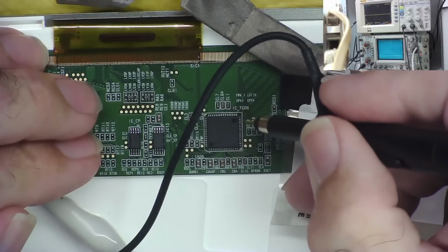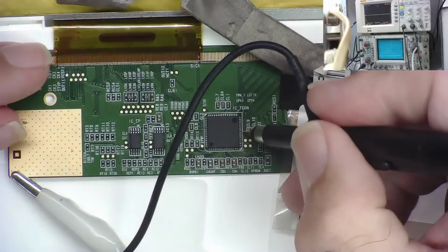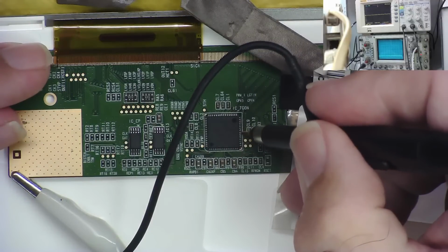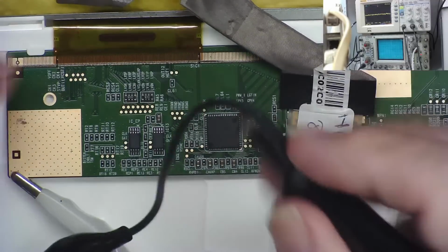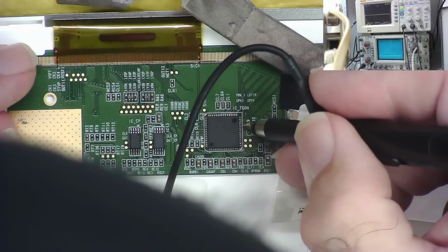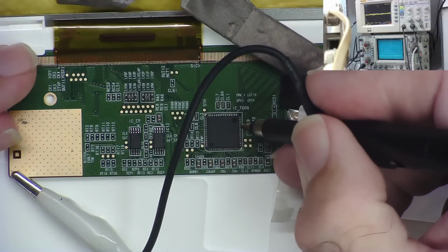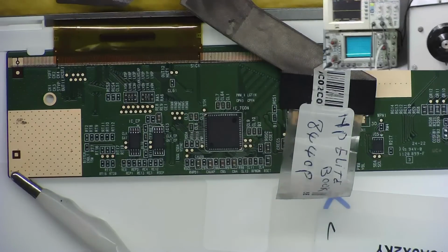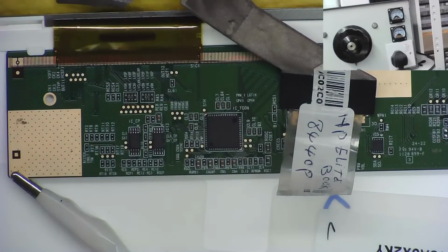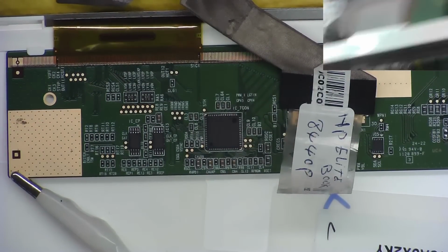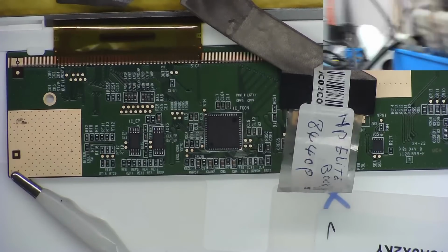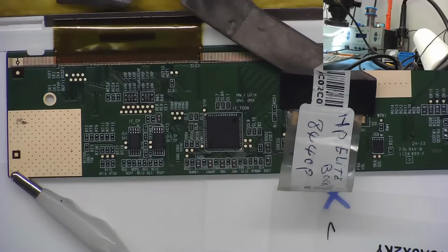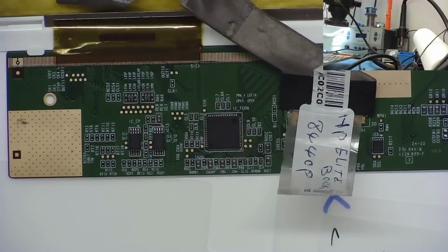Okay, so we can definitely see there's data coming out of this chip. I'll just try and find another one. Yeah, you can see the data pattern there on the scope. So there's data coming out of that chip. What we need to do is have a look on the other one, the bad one, and see if there's any data coming out of that. I should still have a picture on this screen in case I've just shorted something up. I don't think I did. Yeah, picture's still on the screen.